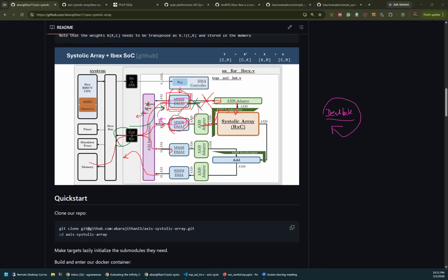And I found that the problem is not in the access protocol, or in the design assumptions. It arises due to the specific nature of this problem, where you need to synchronize two things to go in, and both of them are taking data from the memory, and these DMAs are being too greedy. When all these things come together, you have a deadlock.